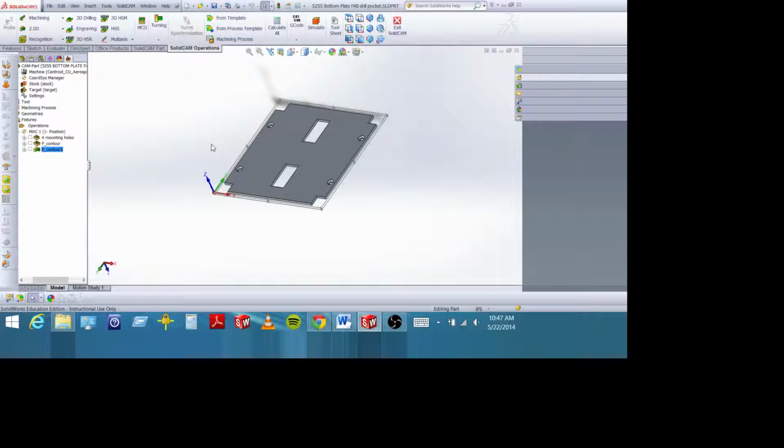There's multiple answers to this problem. You could do something crazy. You could drill and tap these 4 holes in the plate that's underneath, and screw this down, and then you could just run around it. It's a little bit of work, but you could do it. There's a more common method that we use, and that is we'll put clamps from one side and cut only half of the part. Then we'll flip the clamps over and cut the other half of the part. It's such a common method that I want to show you how to do it.